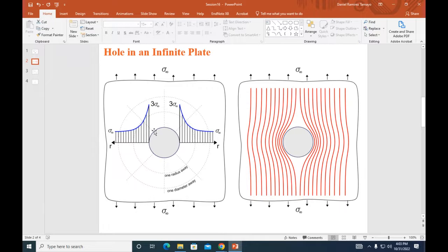You guys can imagine that if we make this hole a radius of 0.0000, really small, that's basically the same thing as having a crack, right? And whenever we have a crack, we know that the stress on that crack is more than it is supposed to be without the presence of the crack, and that is what causes the crack to propagate within the body, all right?